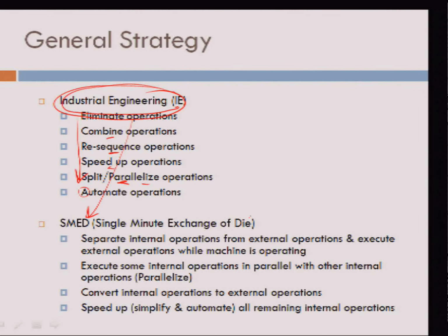So our strategy for tooling analysis as applied to setup reduction would essentially be to take industrial engineering and then combine that with Shigeo's brilliance, which is his setup reduction process. And at that time, since he had begun by applying that to reducing die changeover on presses, he called that single minute exchange of dies. And so a very powerful thought process that he came up with was, you look at the activities being performed and you try to separate them into internal operations, that is, the machine has to be idle for those activities to be done, and then as much as you can, take the work off the machine so that even as the machine is in operation on the previous order, you could be performing these setup activities in parallel, preparing the machine for the next operation.